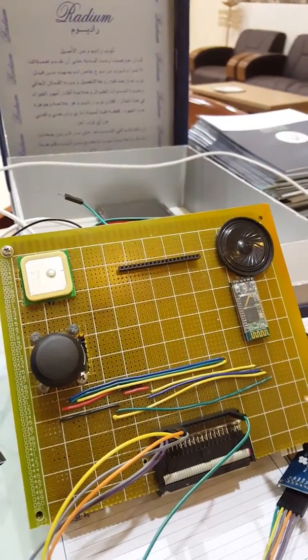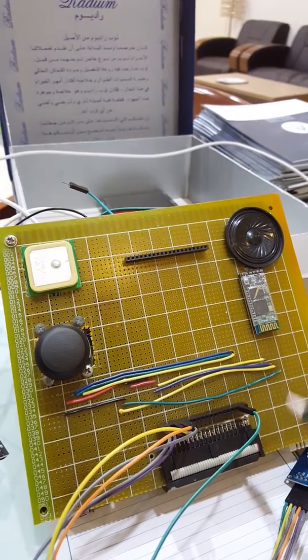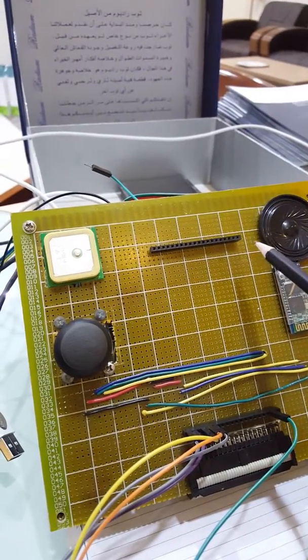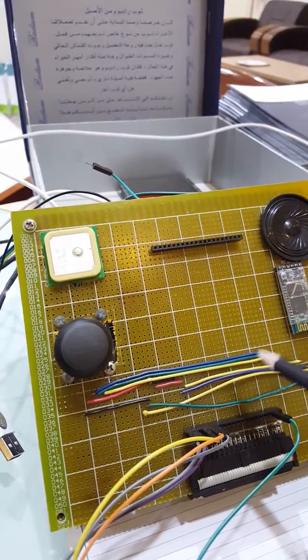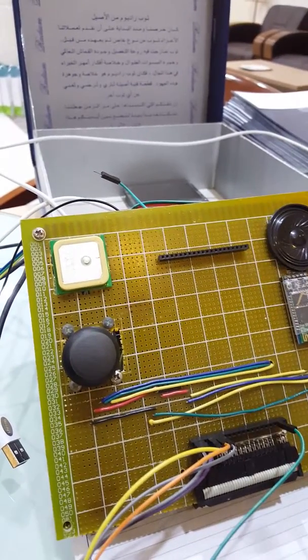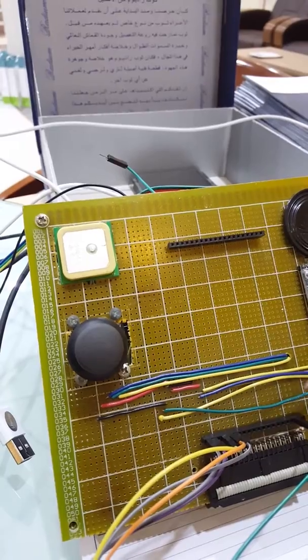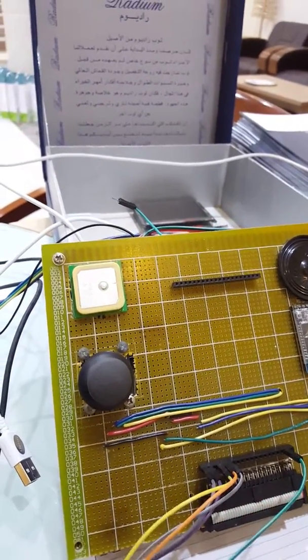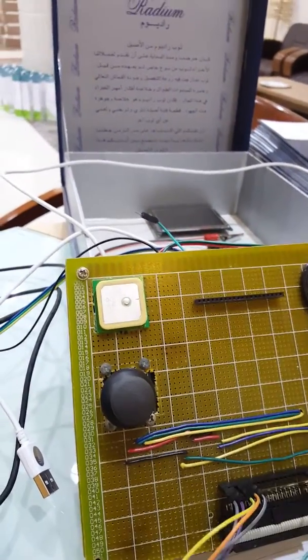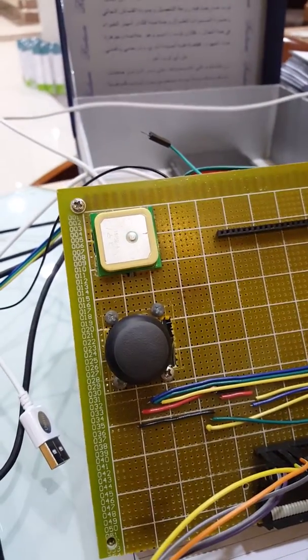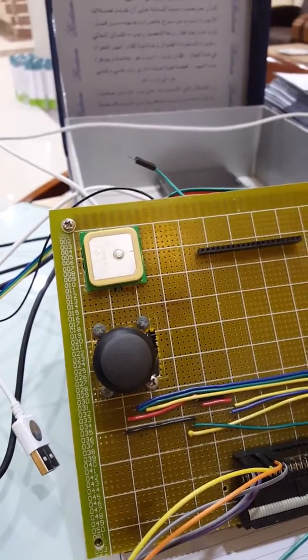So here is my setup for now. Do you remember the development board that I had before for the Adafruit TFT? For this development, I just disconnected the old one, the Adafruit TFT, and connected this SD card reader to the same pins of MISO and MOSI and SCK and so on.